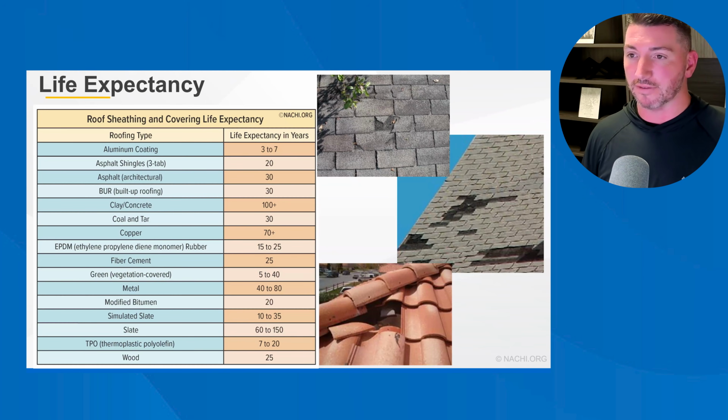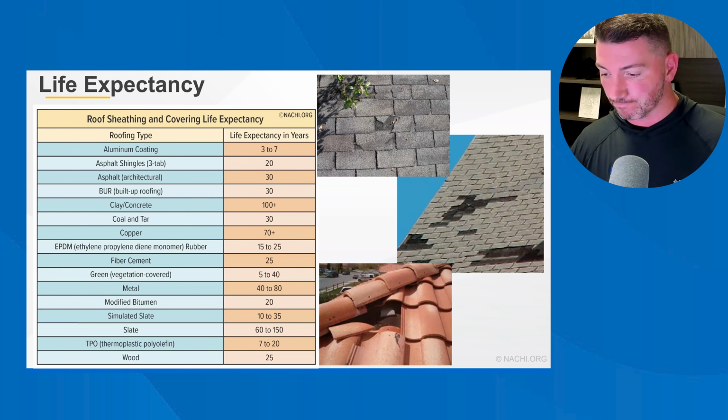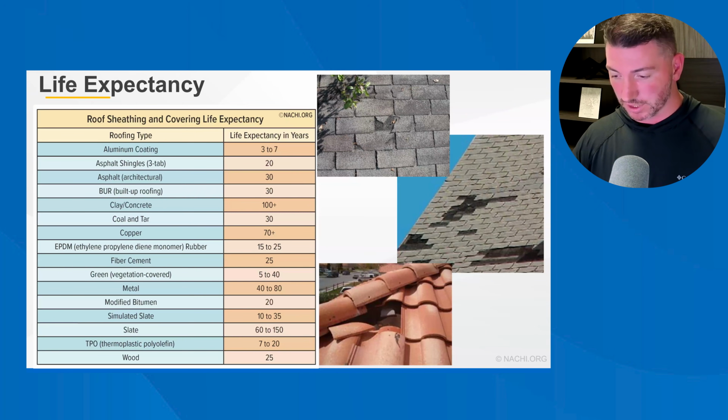It's just completely different when you have sun exposure, UV. There's a lot of different things, but the hot climates really degrade roofs a lot faster. They drastically reduce the shingle life if you're using asphalt shingles. And that's why in places like Florida, for reasons of wind and hurricanes, but also for life expectancy, you'll see a lot of clay tile roofs, whereas in Massachusetts and New York, you see a lot of shingled roofs. You see a lot of slate roofs too, but they're usually 100 years old.